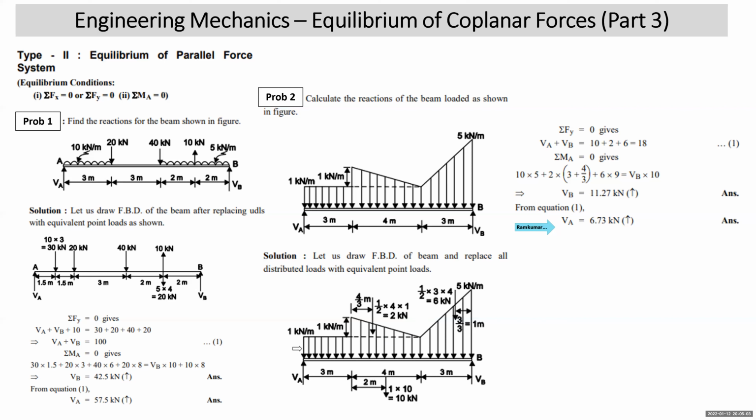All right. We understood how to select the moment center. We should also understand how we get clockwise moment or anti-clockwise moment, although we have discussed it at length in the resultant chapter. When you take moment about A, you can assume that you are keeping a pencil or a pen at A perpendicular to the diagram, or perpendicular to the page, and assume that this bar is free to rotate about an axis through point A.